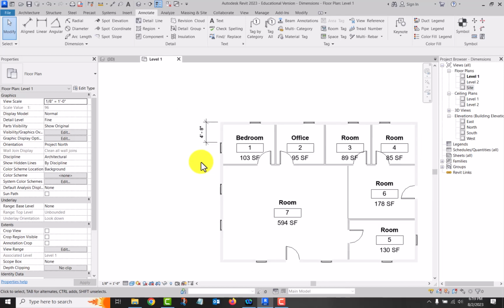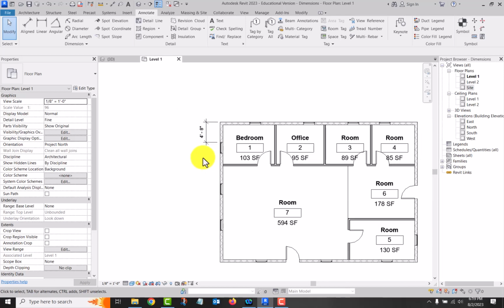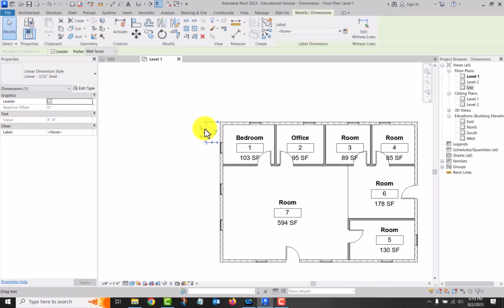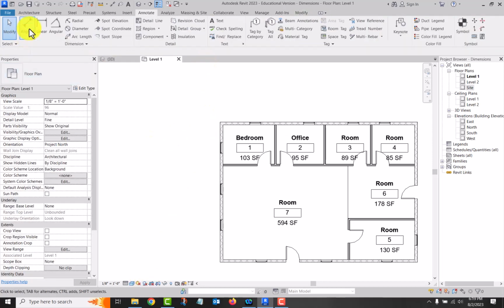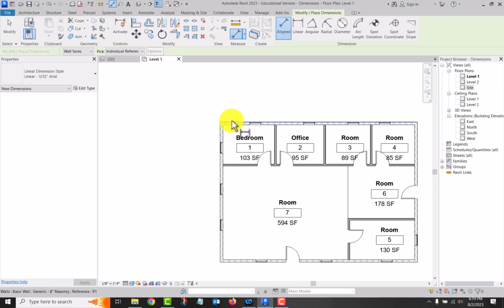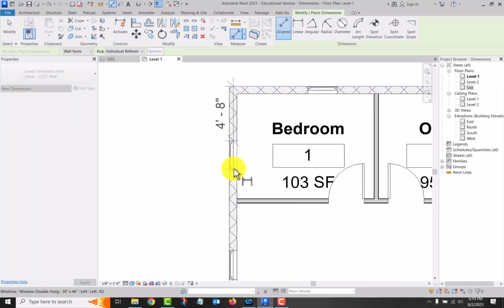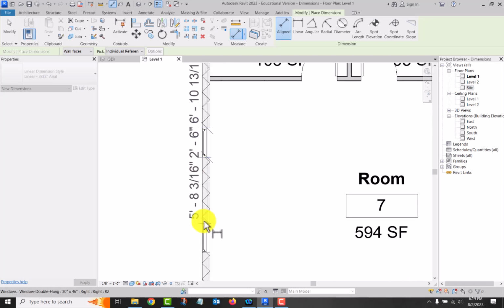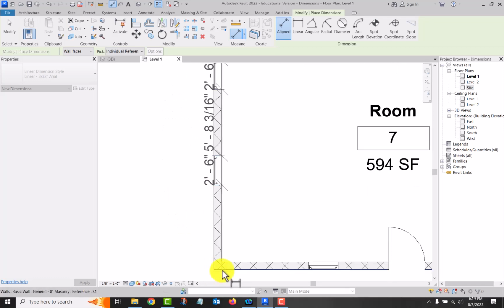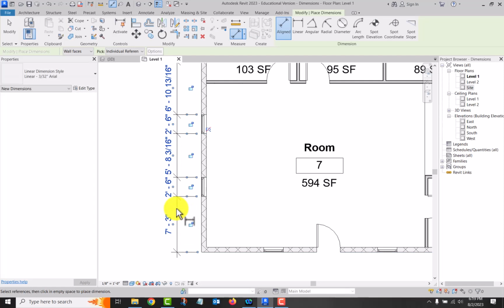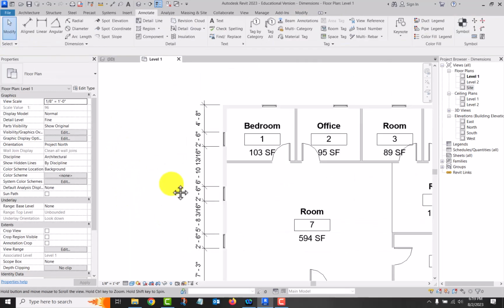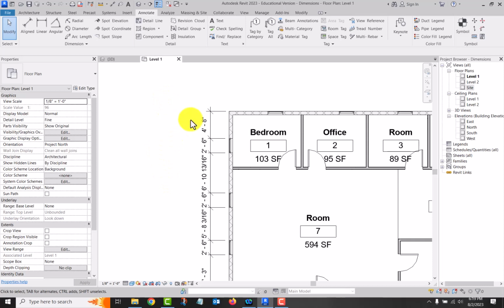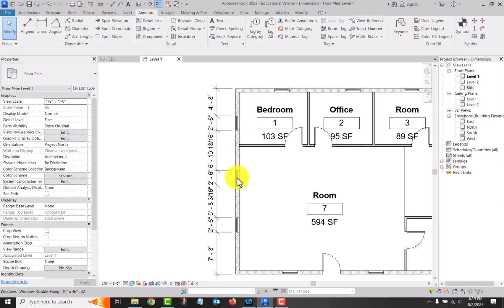Usually when you're dimensioning through a whole series like that, it's best if you go ahead and dimension everything in that chain. So we'll go align. And I'll just go ahead and hit all of these, and then pull it out and place it. Okay, and so there it is. And so now, if I wanted to, I could edit these, get these windows lined up where I want them. One thing you'll see, okay, so let's go to this window here.